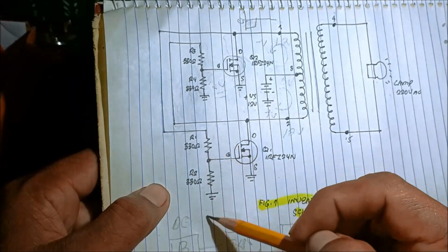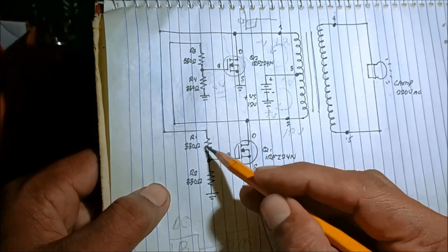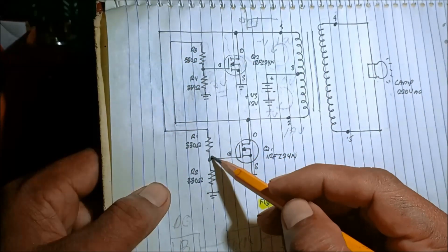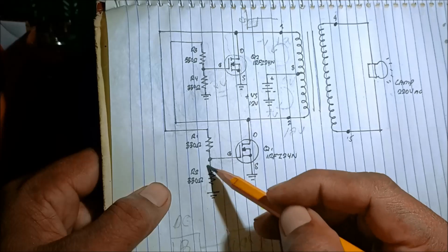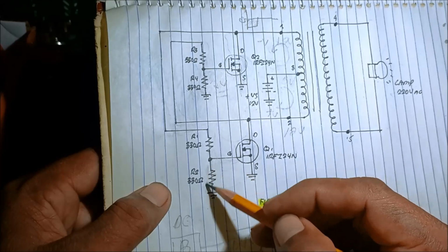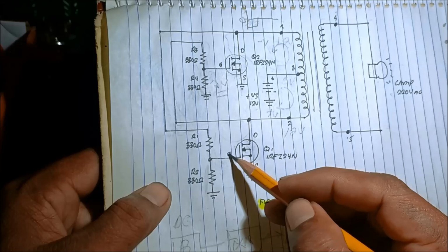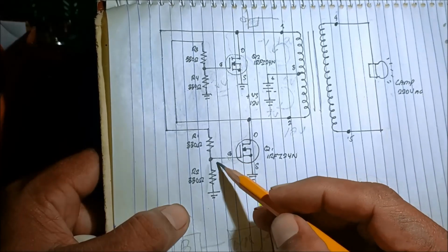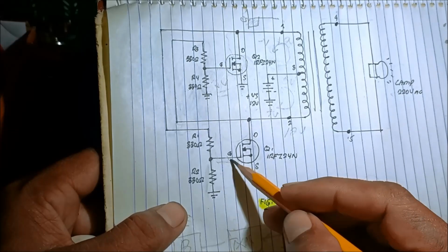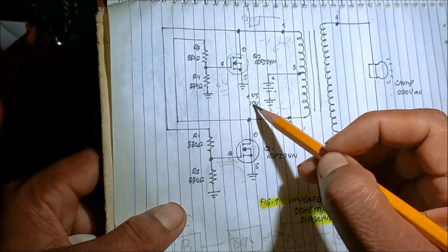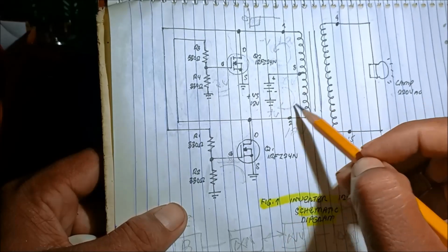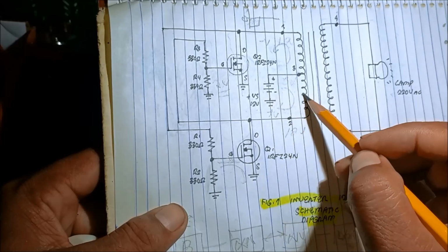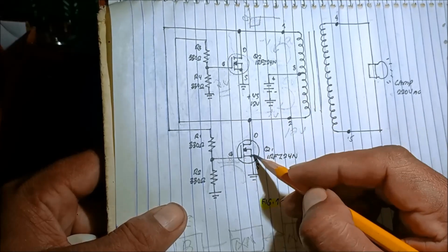feeding to the resistor or switching this MOSFET on, since there's a current that flows into the gate, into the resistor gate, causing a voltage to develop across gate to source. So when there's a voltage developed across gate to source, this MOSFET will switch on. So it will switch on now. The current from the other side, the clockwise, will now flow from drain to source, from the battery to the transformer, from drain to source. So it will switch on.